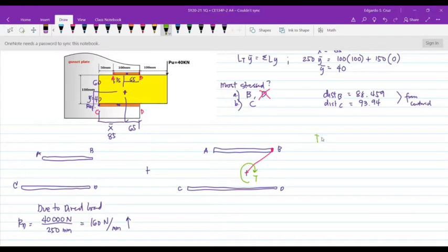Okay, so solve natin muna yung moment T. Moment T is equal to 40,000 newtons times the distance. So what's the distance? So here is the distance, E. Okay, how much is the eccentricity? So that would be 250 minus X bar. Okay, so yan yung magnitude ng moment din natin. Times 250 minus 85. Pag kami mali ako, please let me know. So that is 6600 times 10 to the 3. And the unit of which is Newton millimeter. Okay, and that is clockwise.